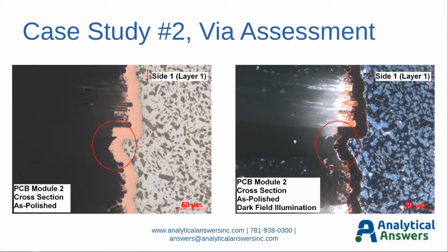Here's a resin-rich region here. These are glass fibers that we're looking at longitudinally, and these are glass fibers that we're looking at in the transverse orientation. And again, this resin-rich region was etched back slightly more than the fibers were when they did their etch back after the hole was drilled.